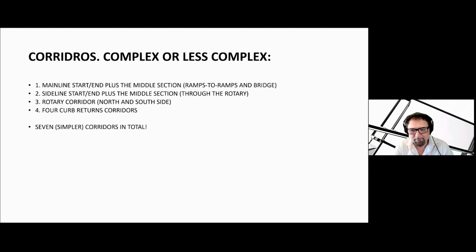So the big decision time is what type of corridor, how will I split my corridor? I decided to create a separate corridor for each one of those alignments. First of all, because they have a lot of dependency between each other, and also because I really wanted lighter corridor models to deal with targeting and so on. Also, each one of these corridors will have multiple regions, and so each region will require the maintenance of the target. So I'll explain all that once we get into the corridor model.